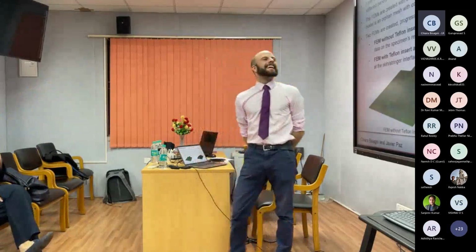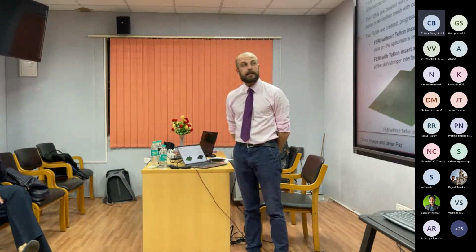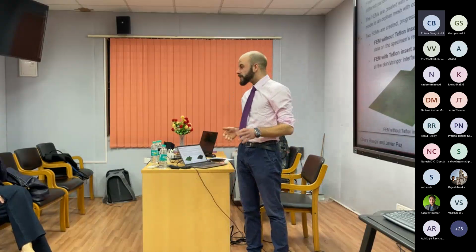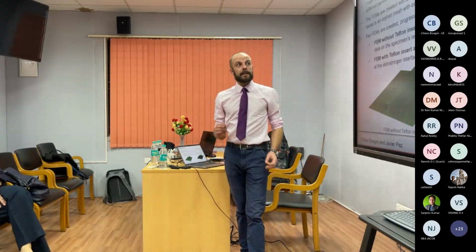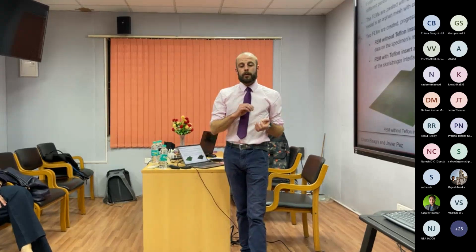So we use finite element models. We can use LS-DYNA, especially for impact simulations, but this work is all done with the Abaqus code. We also use a trick up our sleeve: instead of using the graphical interface, we have Python scripts that we developed within the group to generate the input file directly, what would be the traditional Nastran file back in the day.